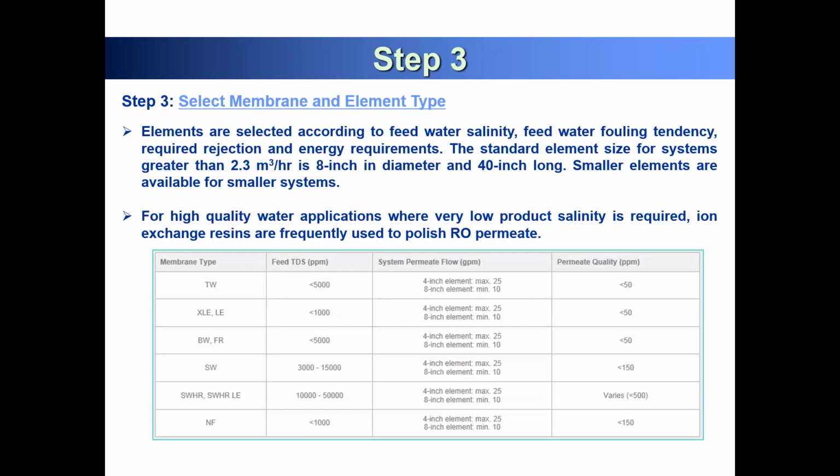So ion exchange resin is like a sand filtration, but rather than sand, you have a resin. This resin specifically removes some specific individual ions. So if you don't want to go for a second pass, if membrane cannot remove some specific ion, you can go for ion exchange resin, which will also be more cost effective than a second pass or third pass.